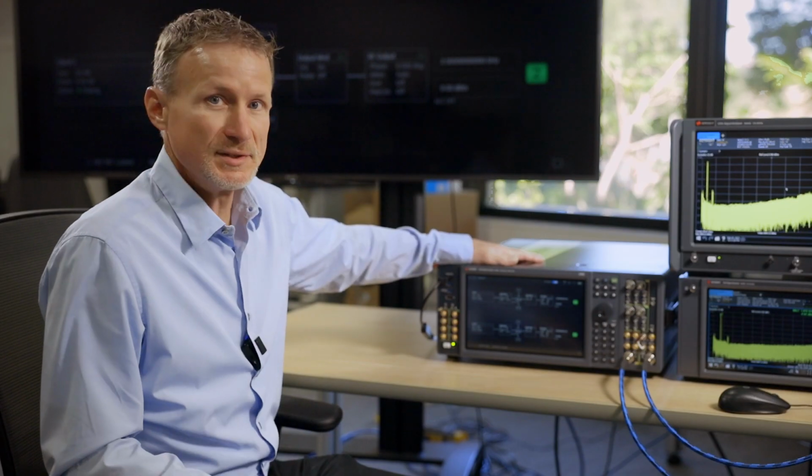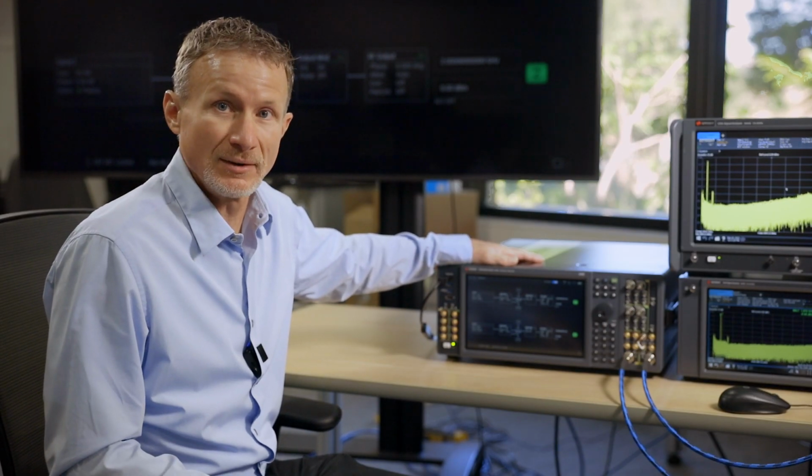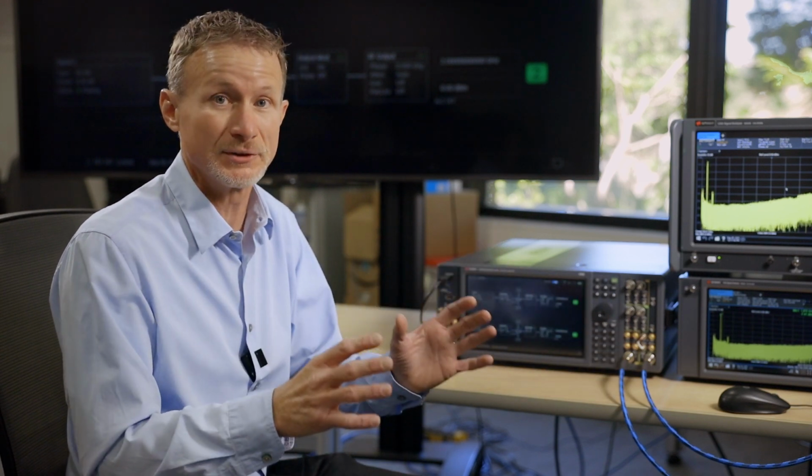In this demo, we'll be using the VXG vector signal generator. As you can see, it has two channels. Each channel can go up to 44 gigahertz. Both channels support high output power capability with great EVM performance, and each channel can support up to 2 gigahertz of bandwidth. In fact, you can actually bond both channels together to give you a contiguous virtual 4 gigahertz wide channel when you need even more bandwidth.